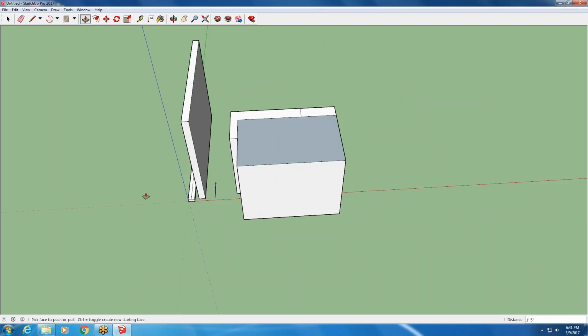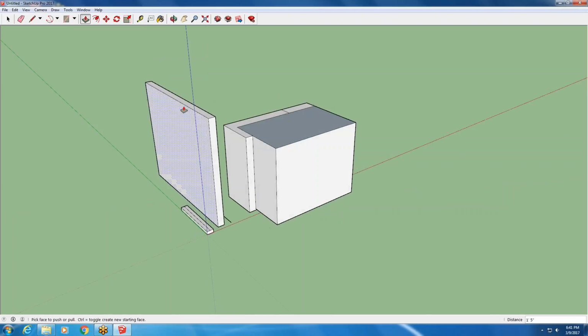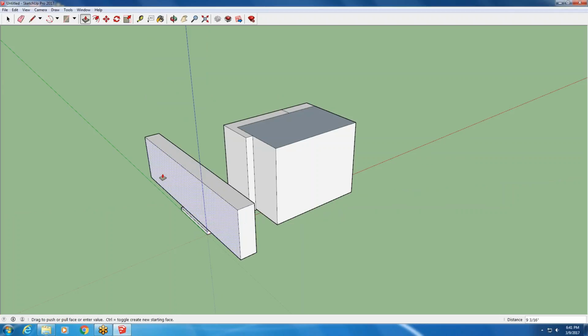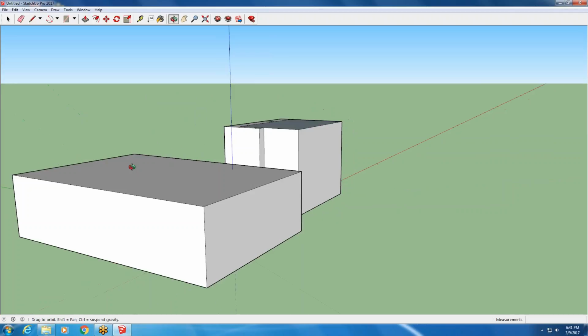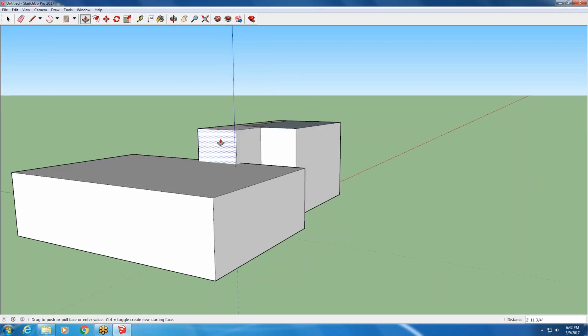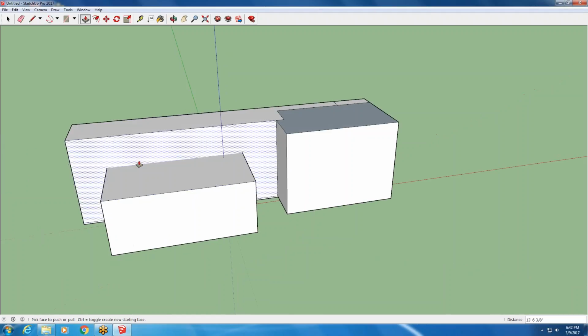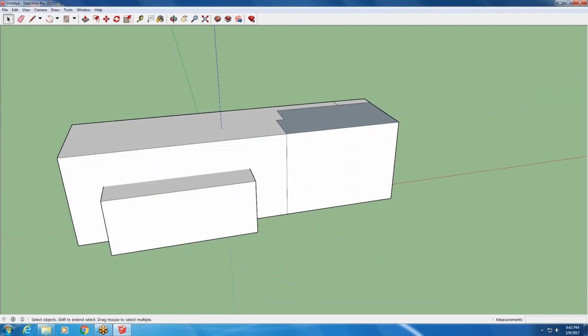drawing an edge splits things. It splits faces. That's what we need to think of that as. Our push-pull tool creates height. We can also bring things down. Things don't only go up. They can go over and out. So it also can create depth. But notice, for as many rectangles as I'm drawing and crossing, they still are lonely and empty on the inside.